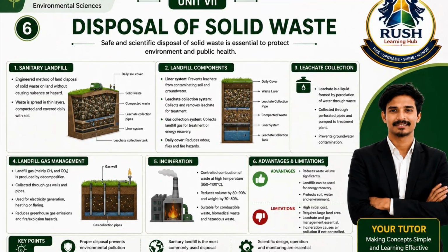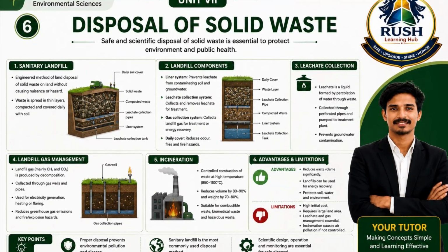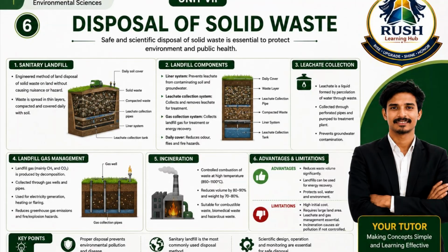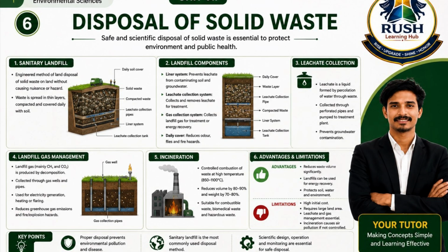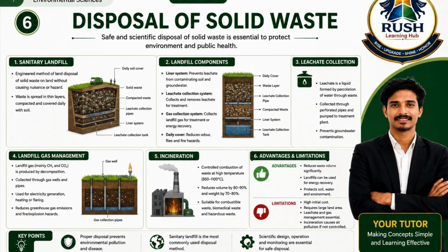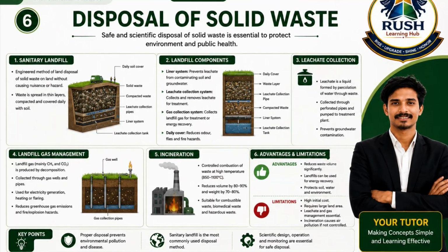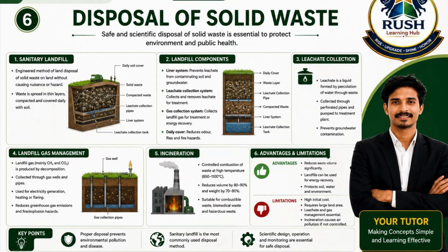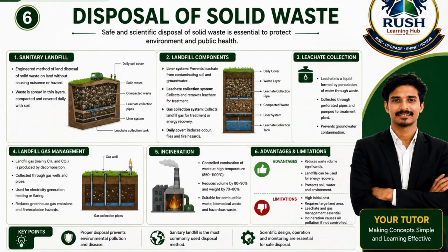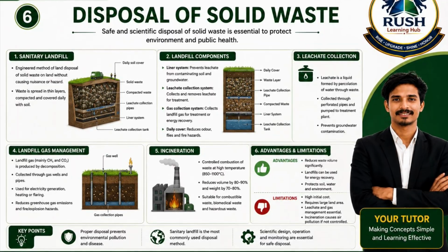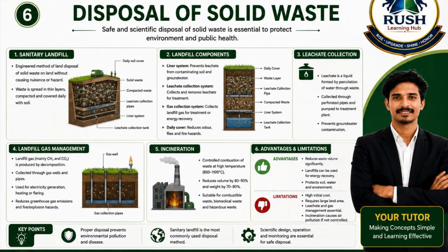Another important component is landfill gas collection. Inside the landfill, biodegradable waste undergoes anaerobic decomposition. During this process, microorganisms produce gases, mainly methane and carbon dioxide. Methane is highly combustible and is also a powerful greenhouse gas. Modern sanitary landfills collect methane through gas wells and pipelines. Instead of allowing methane to escape into the atmosphere, it is used to generate electricity or heat. This helps reduce greenhouse gas emissions while producing renewable energy.